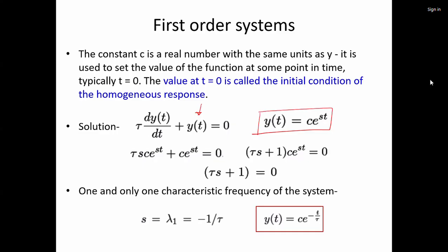So that is why we are going through this math. It will give you some generic idea about different kinds of systems. First order and second order systems are not only specific to temperature, pressure, and so on. They are generic. You can talk about even mechanical systems like a spring mass dashpot system. It is a second order system. So you have to understand the orders of system. That is why we are going through this math.